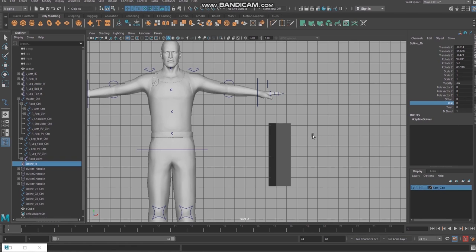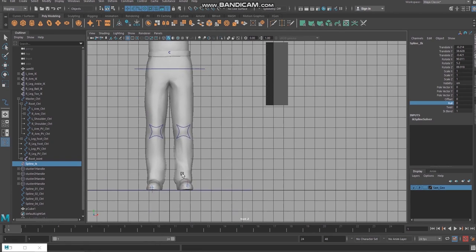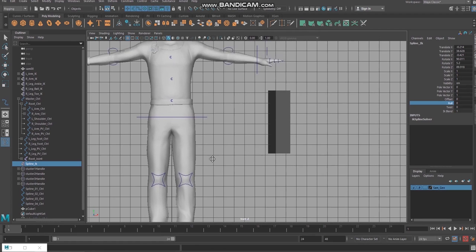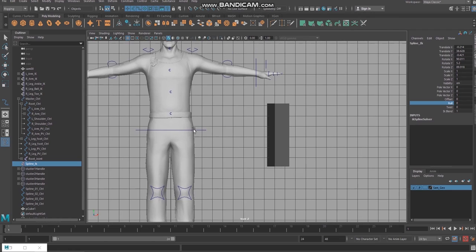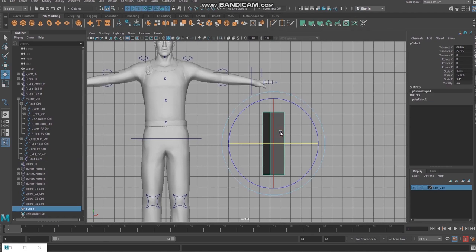Here the main difference in the roll option in spline IK and this example is that this roll is getting twisted, but the extension of the root joint is coming down all the way here, which has IK handles, 1, 2, 3 IK handles for one side and the other 3 IK handles for the other side. Other constraints and all these things are here, so it cannot be completely rolled. It is getting some deformation in the skin, but I hope you understand. In this case it is called the roll. So this is the difference between twist and the roll.